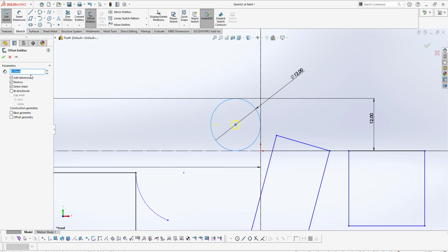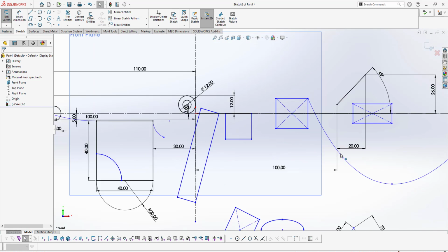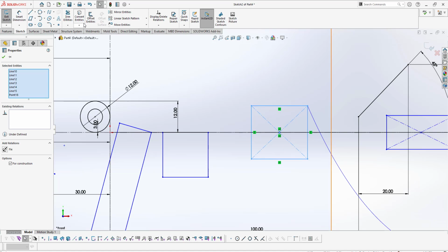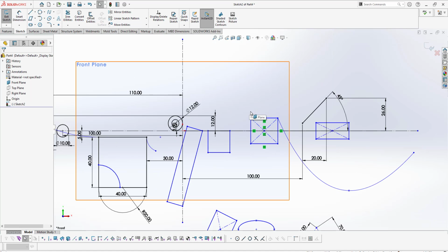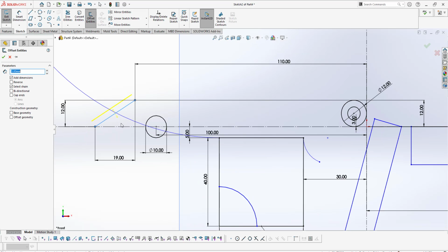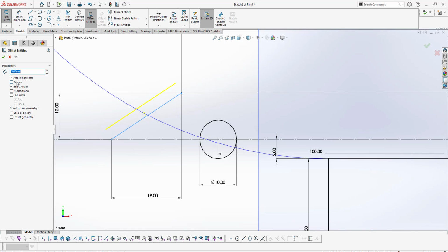Okay, at 3 mm. Okay, super. So now I am going to offset this rectangle. Offset this line. Offset means it offsetted 3 mm. We can reverse this line. So suppose we need this line as a cap end, we can choose cap end in arc condition or in line condition. We can close this line as a box line.